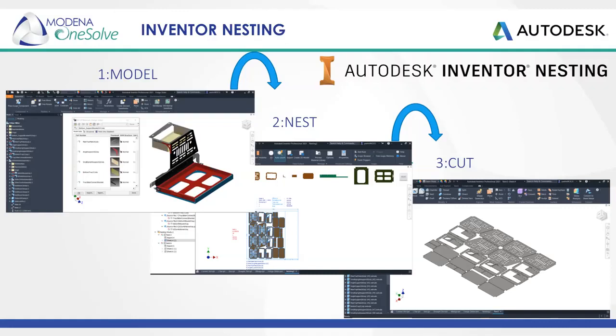The last phase, cut. There are two options to get your nesting data out for manufacturing. The first is your nest can be quickly exported to a DXF that can be used with a cutting machine. Or alternatively, a 3D model can be generated and used in conjunction with Inventor CAM to simulate the cutting operation.